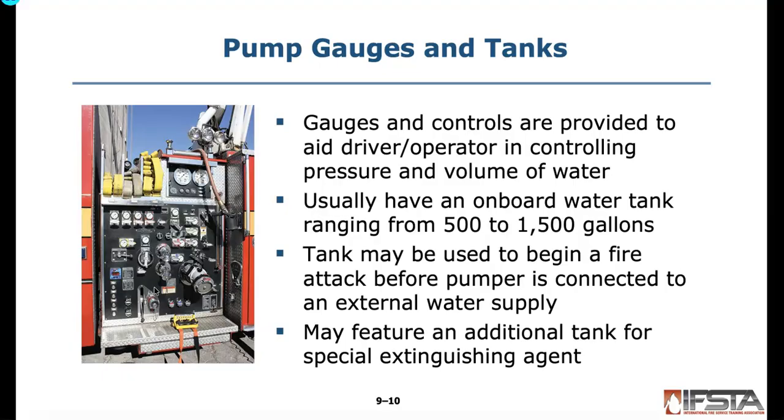Okay, so that's how that works, right? You don't want to draw too much water out of your tank, or you'll end up cavitating the pump. So you have to make sure you have a water supply established at some point before you use up all the water in your tank.